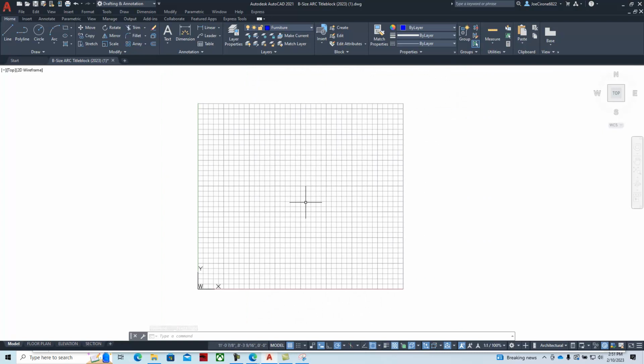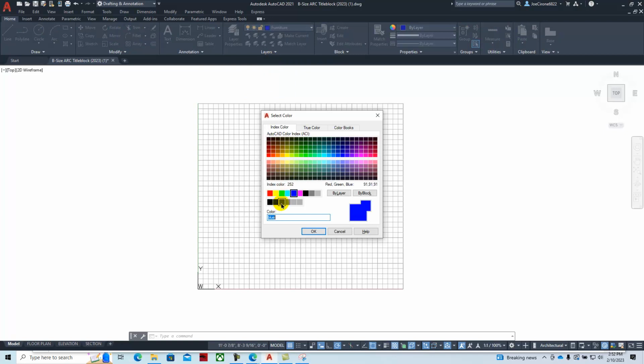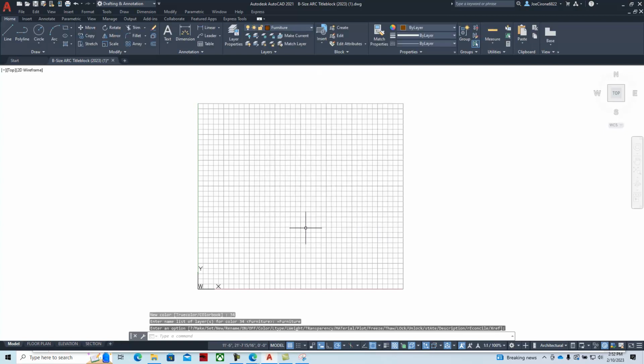As we start to work with 3D objects, we'll start off by drawing the 2 discs for the table. And I think I'm going to change my furniture layer color to brown. You can do that by clicking on the blue swatch, and we'll make that a shade of brown. We'll start off by making a 2-foot diameter.